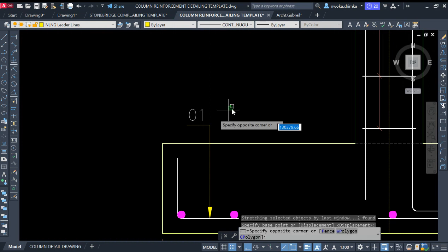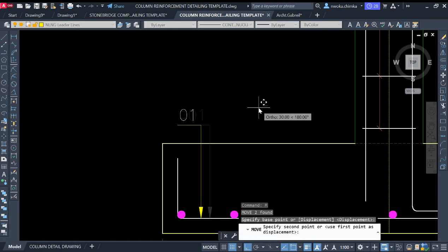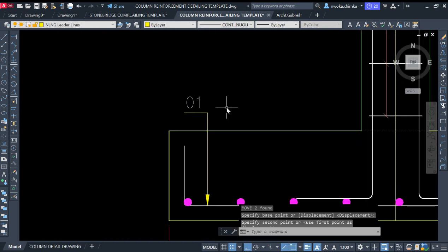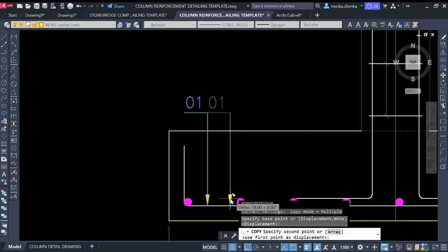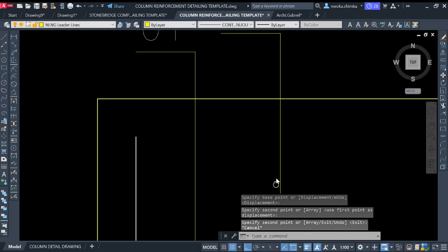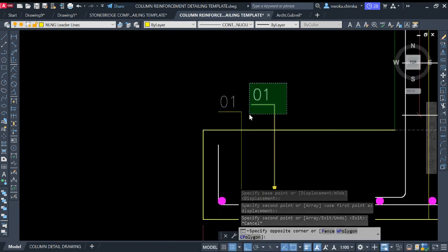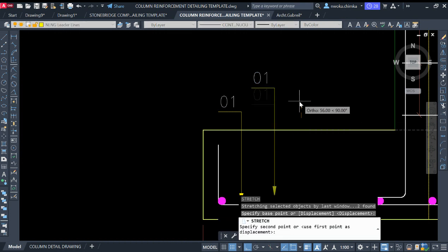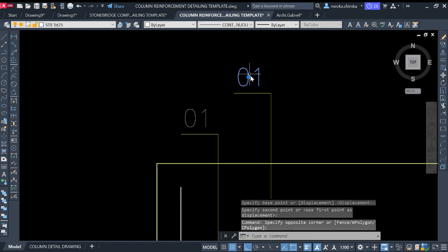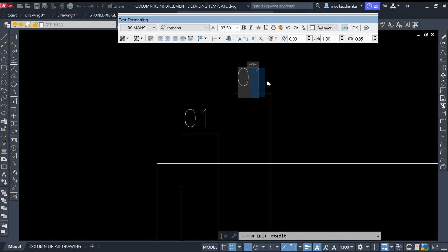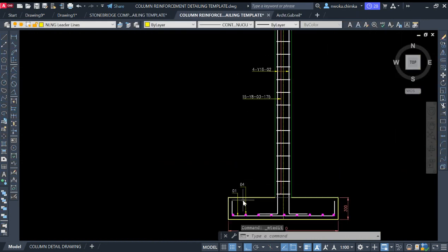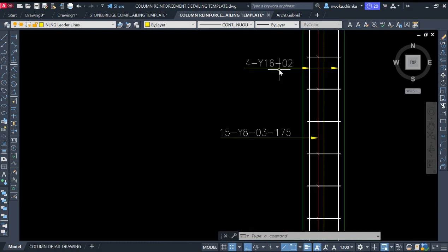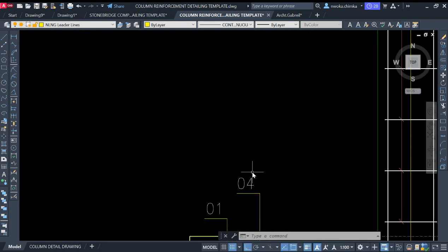Then I'll move this a bit forward, and copy this again. I'll show this bar mark again, point at this bar also, take it upward and stretch it a bit, and call this bar mark O4. Okay, and keep this here. So right now we have bar mark O1, bar mark O2, O3, and then O4.